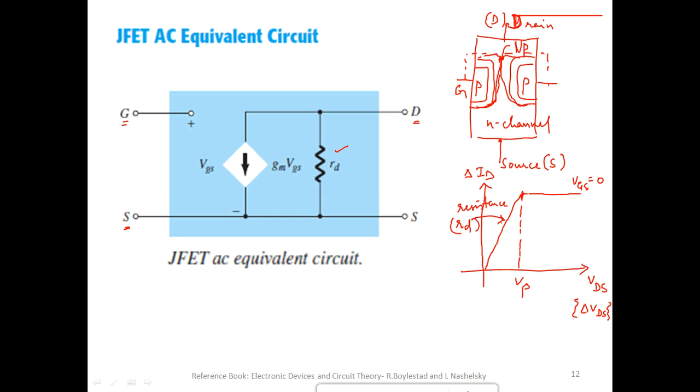When the current saturates, we mean that there is a constant current source, it is not changing. So after pinch off, we are in this path. Before pinch off, the current flows across this path. After pinch off, it is just a constant current source that takes over. Fine. So that's the current IDS.